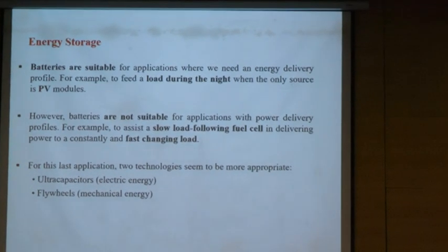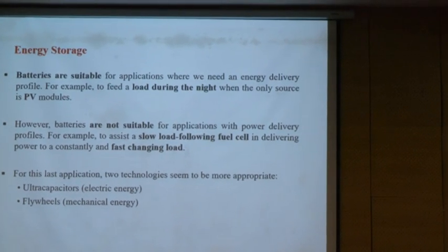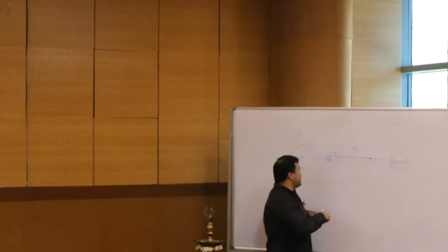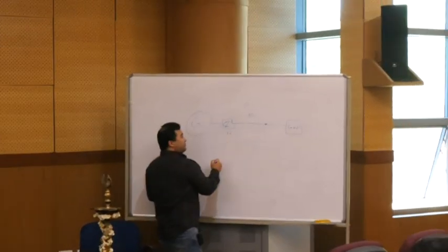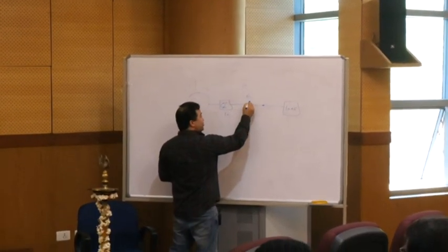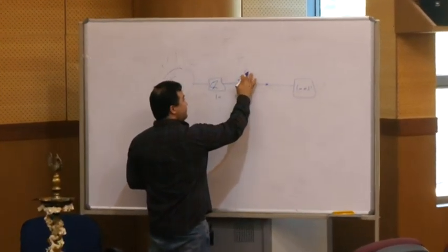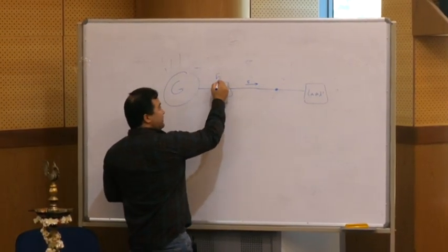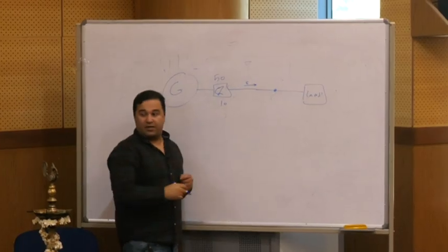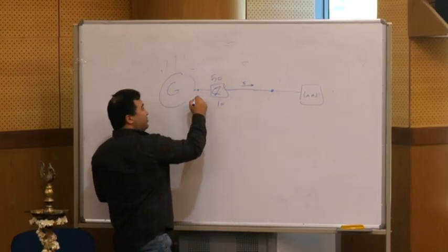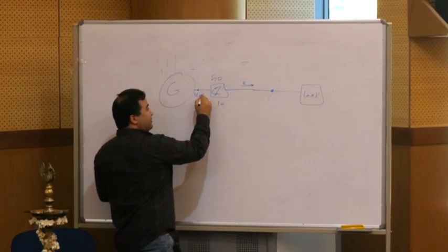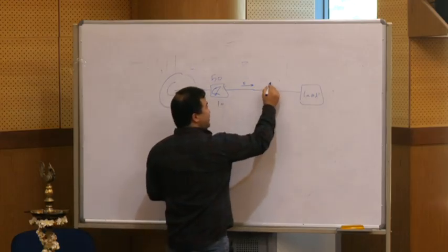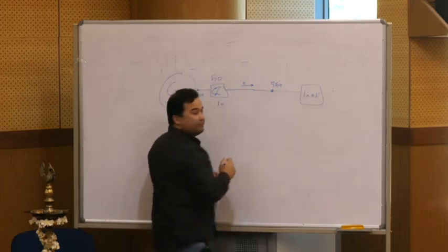And this is the point of common coupling, actually, the connection between load and generation, okay? So assuming Z is 10, and the current is 5, so the voltage drop is 50 here. And if the source is 400, the voltage is 350 here.